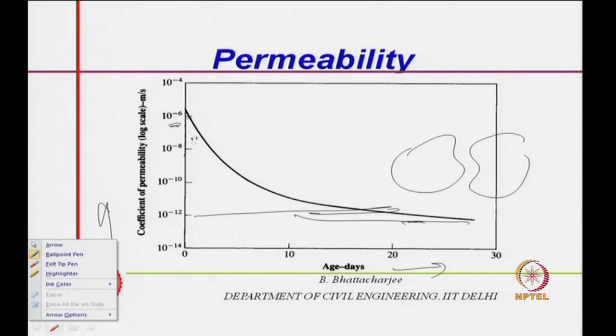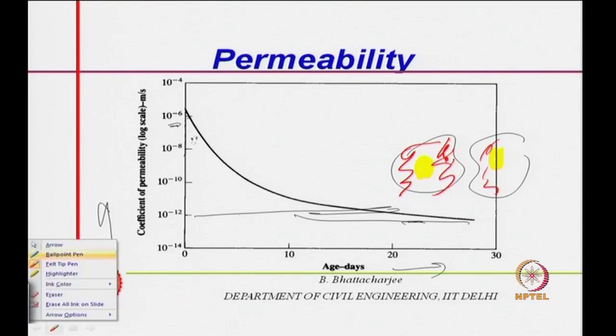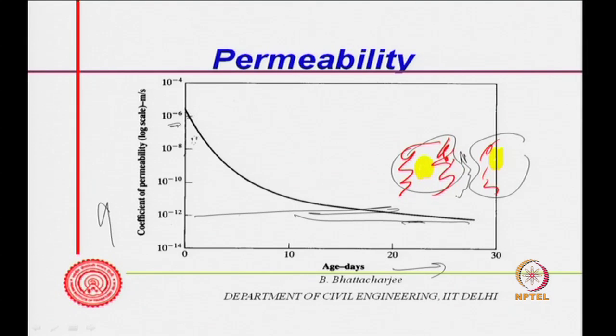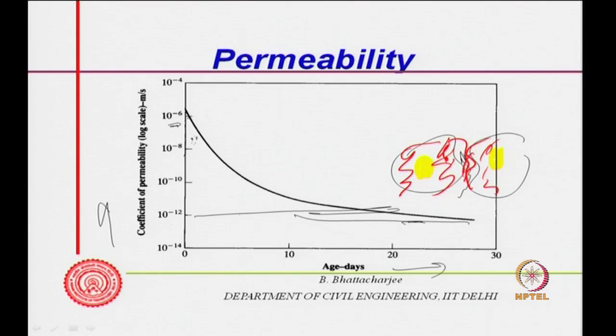So, if you recall, this is our cement particle, and this is the hydrated cement around, and if you have more hydrated cement around, and this was the water originally, this was the water filled space. As the hydration progresses, this would go and reach there, capillary will get segmented, and we talked of capillary segmentation earlier. Therefore, interconnectivity will get reduced. So, this is related to more hydration: first total capillary will reduce and segmentation will increase, they will be less interconnected, therefore, permeability tends to reduce.